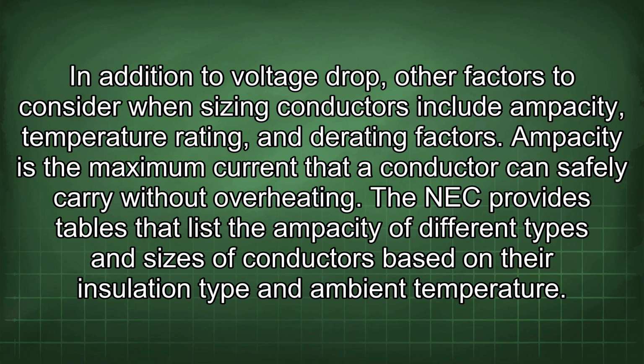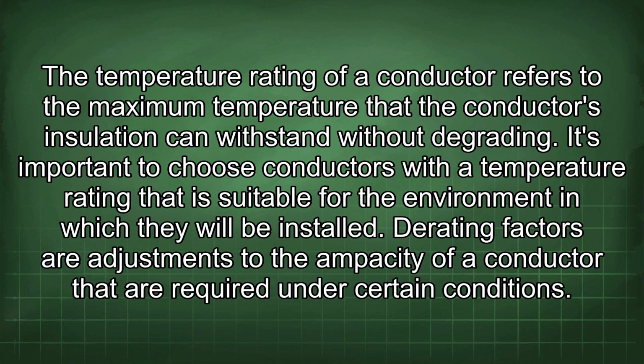Ampacity is the maximum current that a conductor can safely carry without overheating. The NEC provides tables that list the ampacity of different types and sizes of conductors based on their insulation type and ambient temperature. The temperature rating of a conductor refers to the maximum temperature that the conductor's insulation can withstand without degrading. It's important to choose conductors with a temperature rating that is suitable for the environment in which they will be installed.